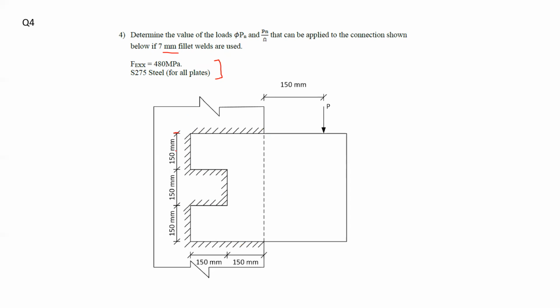Well, let me make this clear. What you have in here does not include the 7 millimeters. So actually your weld goes something like this, plus 7 millimeters, goes down. I'm reaching here, plus 7 millimeters, and it keeps going. So those dimensions that are given to you on the drawing do not include the 7 millimeters. So this is the final shape of the weld that we have.